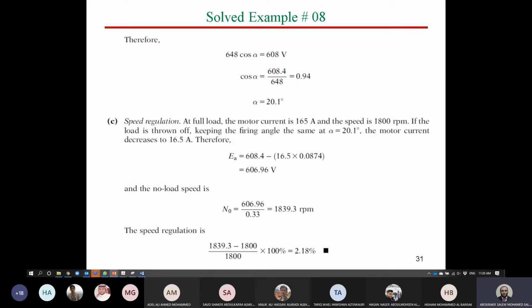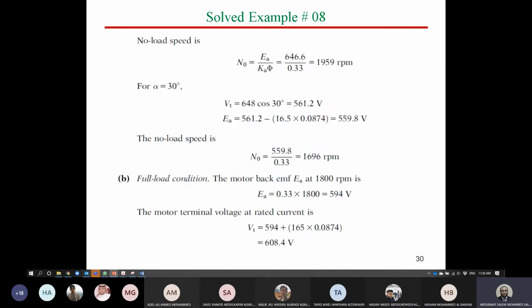But here, because you already make differences or controls both of half cycles, this is called full wave. But the circuit is called full wave semi-controlled. Why semi-controlled? Because you have half of the elements controlled elements and the other half is uncontrolled. So it's called semi-controlled.